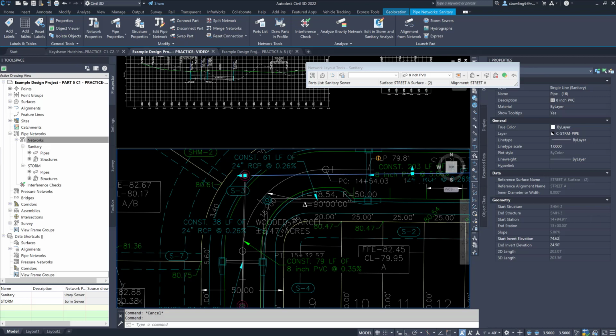When you have 90-degree bends or more, you actually drop 2/10. So I'm going to say 74.52. Now, my end invert is 203 feet away. So I'm going to use the horizontal distance. So 203 times 0.0035 is a drop of 0.71. So I'm going to subtract that from 74.52, and I'm going to get 73.80. Okay, and you can see it's 0.35.